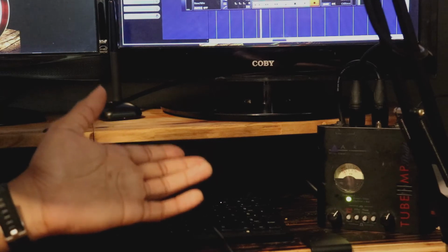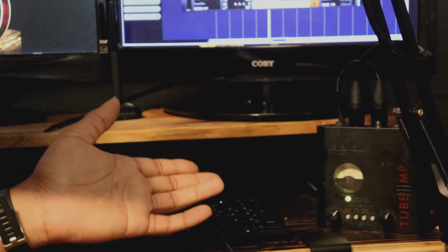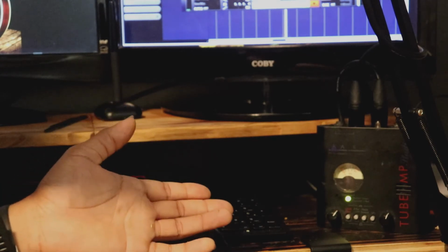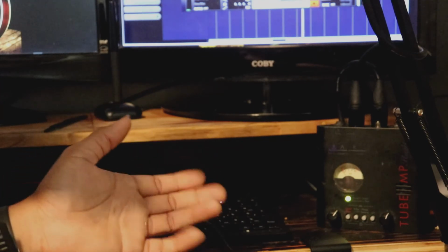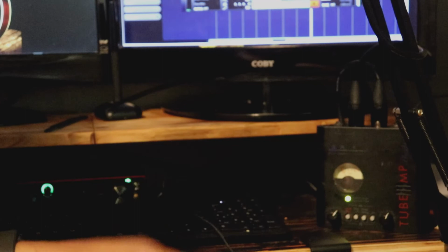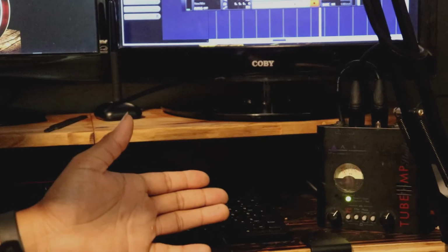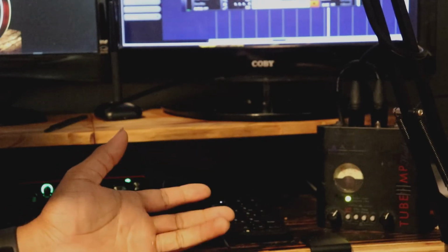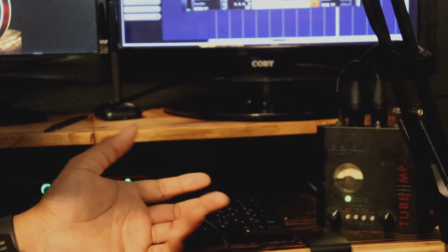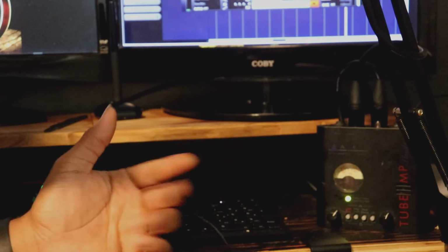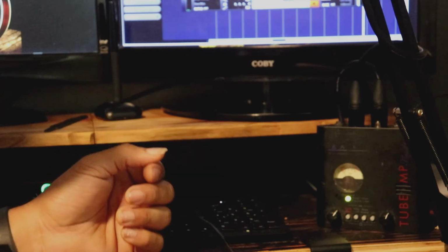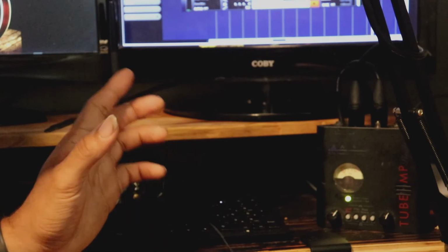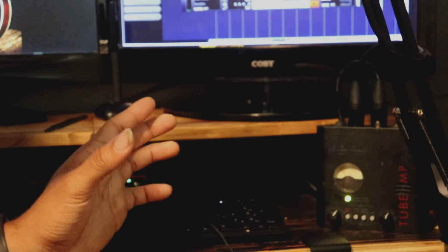Now last night I did some measurements on this preamp, and this preamp will put out 17.5 volts peak to peak, which is about 6.5 volts RMS output. That's if I have all the dials turned up all the way, which right now I have them about 12 o'clock. Of course, in a typical scenario, I won't be turning up the dials all the way, though I wanted to see how much amplitude it could actually supply so I can see how much amplitude I want this EQ to withstand.